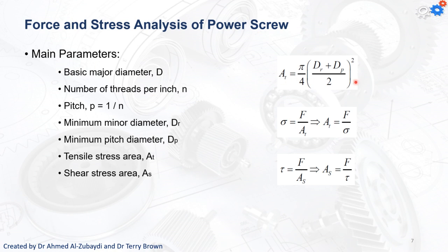If I know the diameters, I can calculate the tensile stress area. If I know the force and the area, I can find the stress. And I can find the tensile stress if I get to know the shear stress area for my thread.